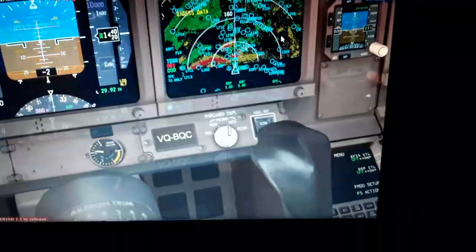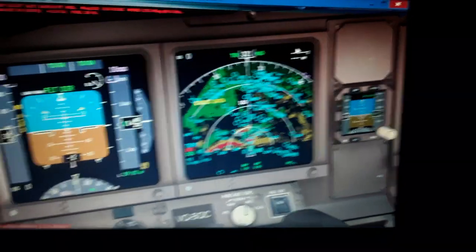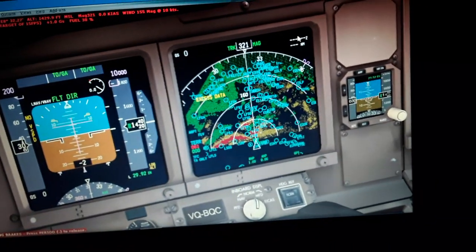We have the flight plan. We create the runways we use for takeoff and landing, magnetic and true heading, the airspeed, the wind, and also the next waypoint which follows. So we use the flight management computer to create a flight plan, a flight path, vertical and horizontal, for the aircraft to follow. I'm going to show you that later also. So this is displayed in the navigation display. So these two displays are the most important for the aircraft navigation because of data, and also in respect of the altitude, horizontal situation indicator, and the altitude of the aircraft.